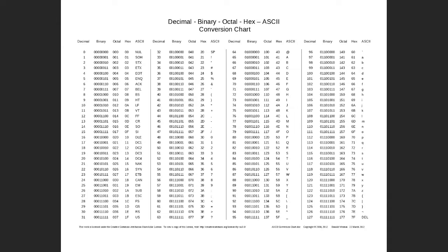That's a natural for PLCs, because a lot of PLCs have 16 connection points on the input module or output module. 16 is a natural number, it's 2 bytes, and so often we'll use a word size of 2 bytes, which means that base 16 is important. So we looked at both of those. We practiced going from both number systems, octal and hex, to decimal and vice versa, so you should be familiar with that.